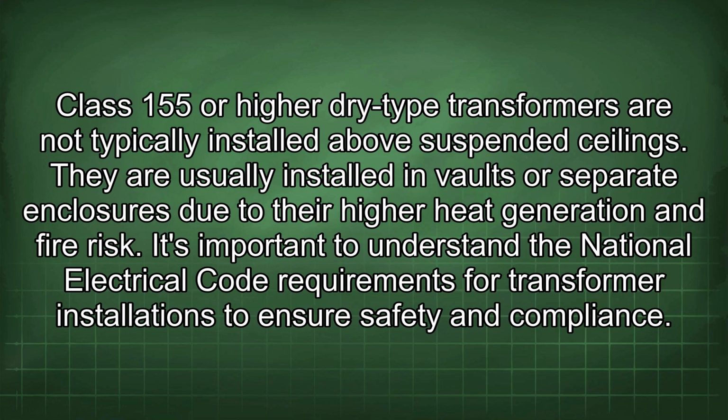Class 155 or higher dry-type transformers are not typically installed above suspended ceilings. They are usually installed in vaults or separate enclosures due to their higher heat generation and fire risk. It's important to understand the National Electrical Code requirements for transformer installations to ensure safety and compliance.